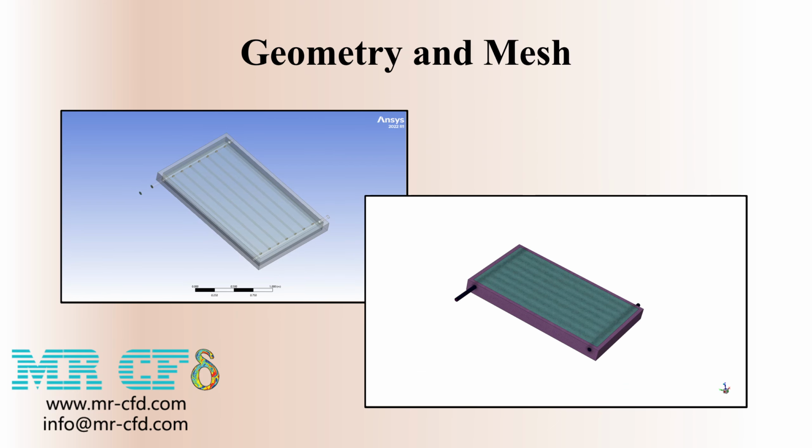The geometry of this project was defined using ANSYS SpaceClaim software and meshed using Fluent Meshing software in Polyhedra type. It must be noted that the whole number of elements created is 2,871,429.